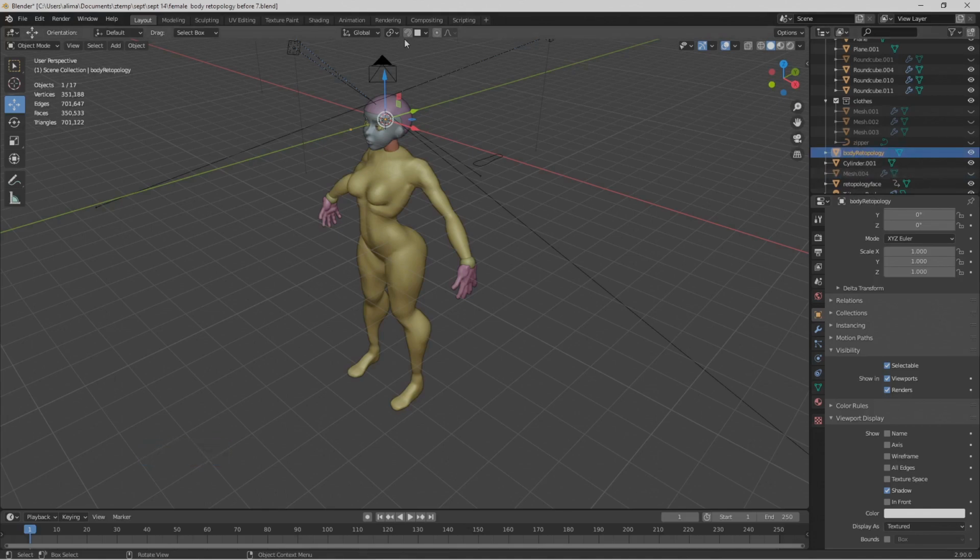We're also going to go to the middle part of our upper screen. This is very important. We're going to turn on snapping in Blender. When I hover over this, you can see that it says snap. So we select that magnet that turns on snapping. Snapping allows geometry to snap to the geometry that's next to it. And that's one of the main things we're going to use.